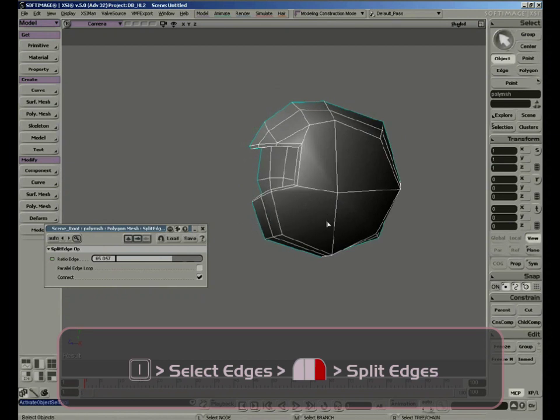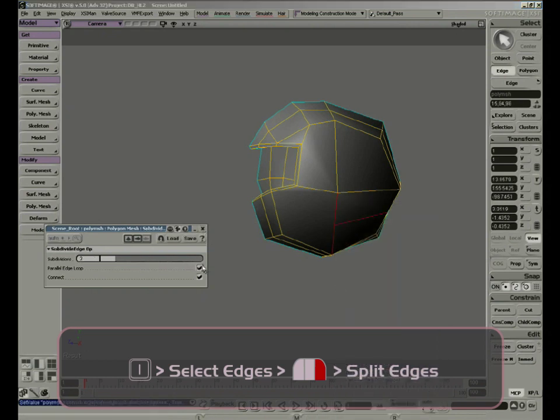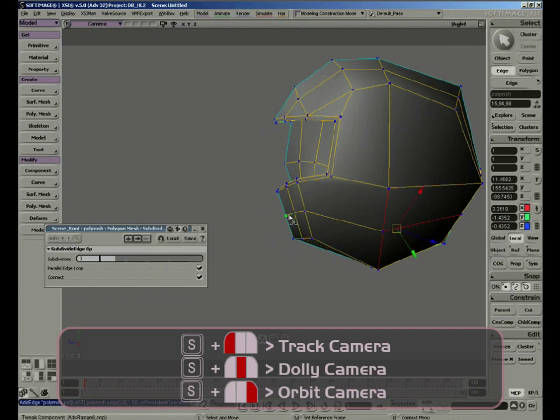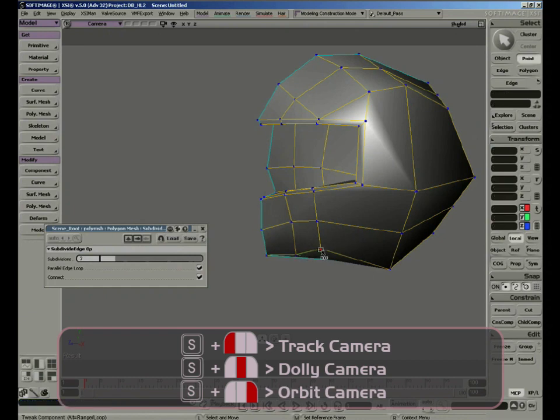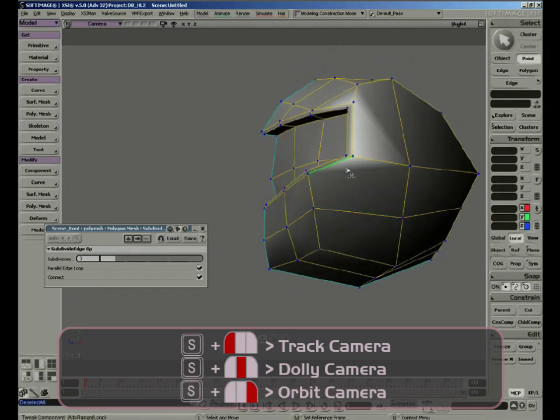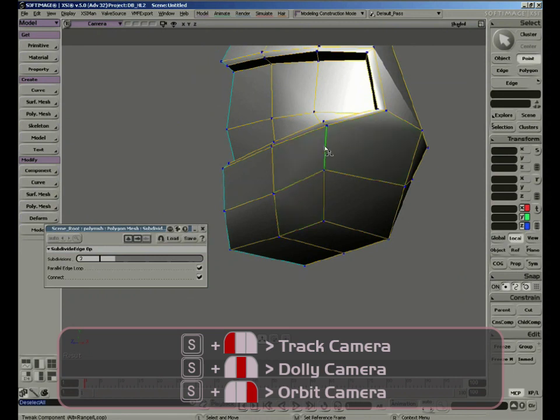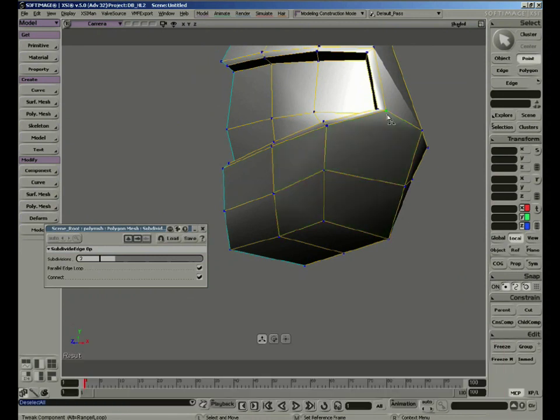So we'll set a border here, select the edge, part of the edge loop, in this case from here to here. We can use the control to make it snap to the center, M to move and adjust a little bit. We're going to try to preserve four-sided polygons and try to avoid these irregular polygons. So make a subdivision, and now we get four-sided polygons.